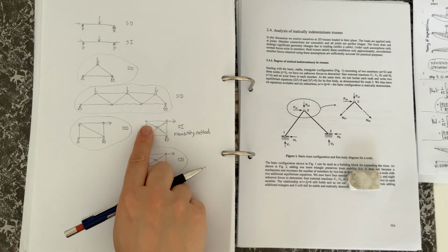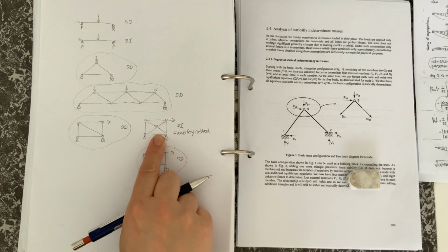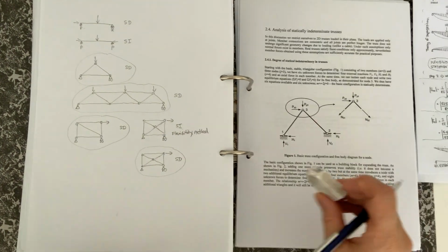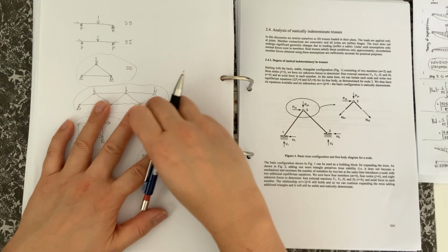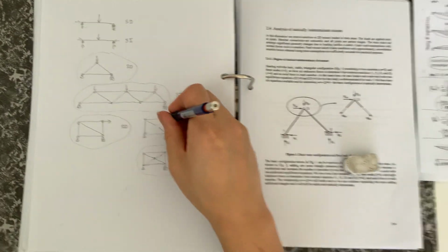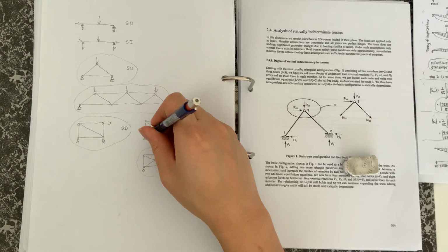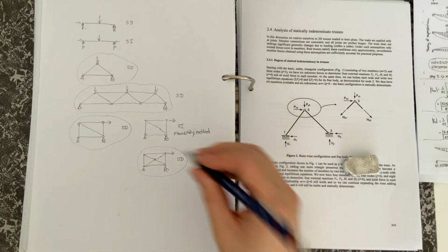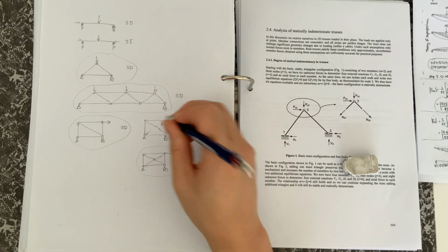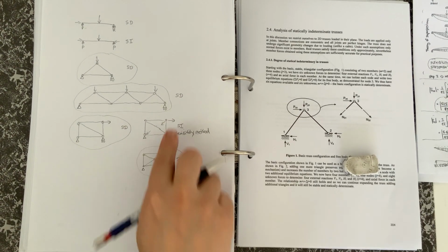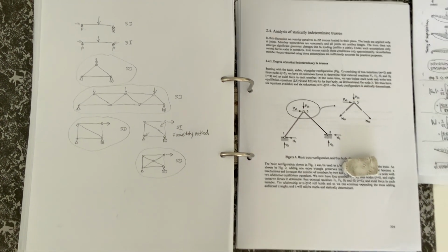In this case here, in order to solve the statically indeterminate problem, we're going to be removing one member that would then restore it to a statically determinate structure, and then we'll be applying a tension or compression force back into the structure to take that into account, and then putting that into a matrix.